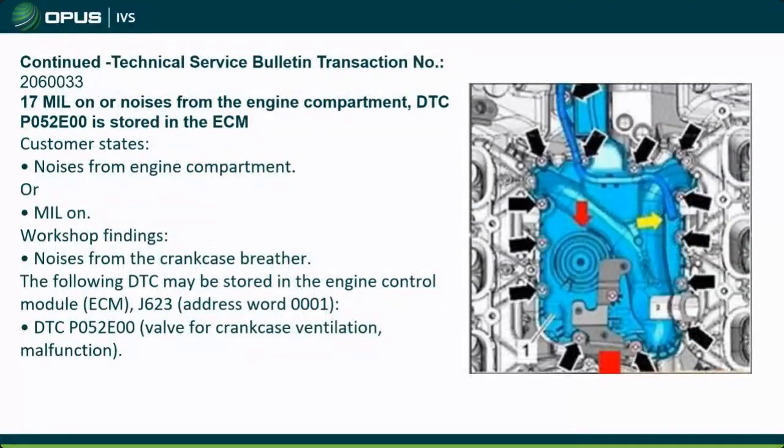There's another TSB for the same exact fault, of course. That makes it a little confusing because you could have multiple issues. Also, noises from the engine compartment, a squealing noise or a whooshing noise from the breather system, which, of course, on this car is under the supercharger. It's not like you can look at it while it's running, right? Because to really get a good eye on this thing, you're pulling the supercharger off, in which case you're not running the engine anymore, right?